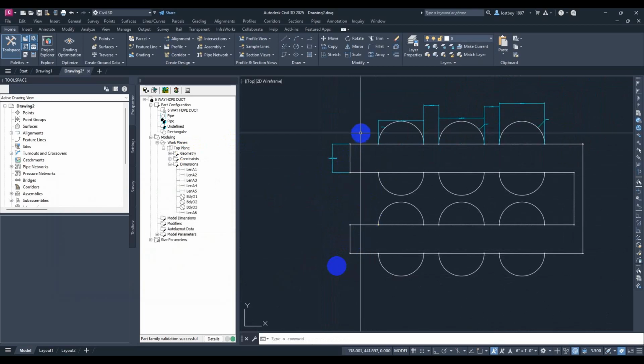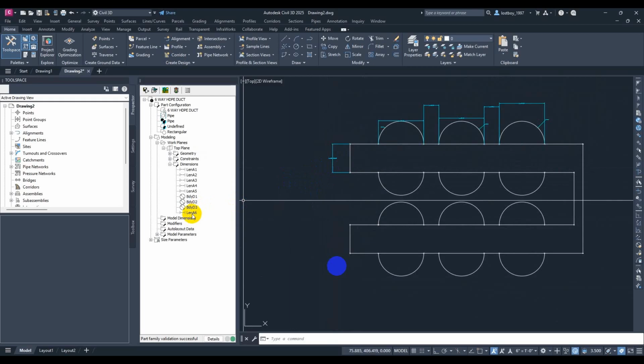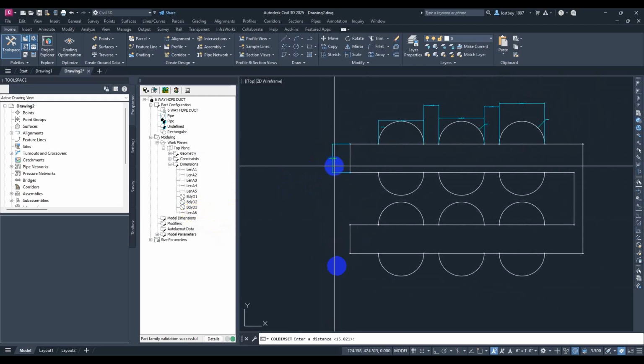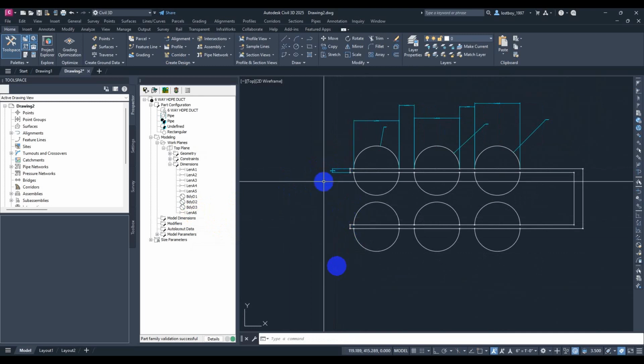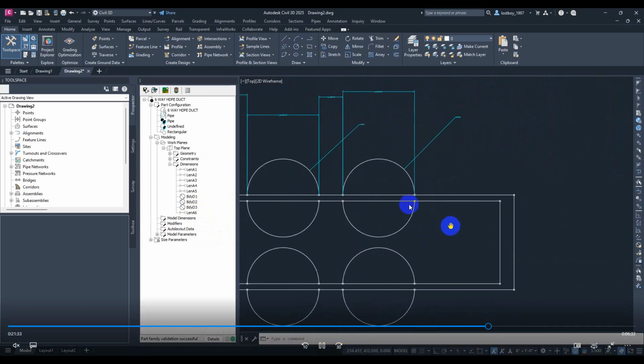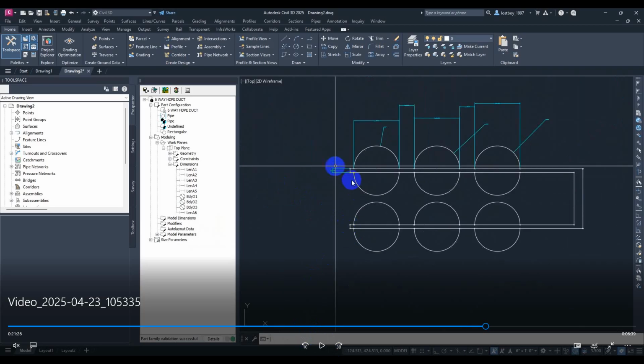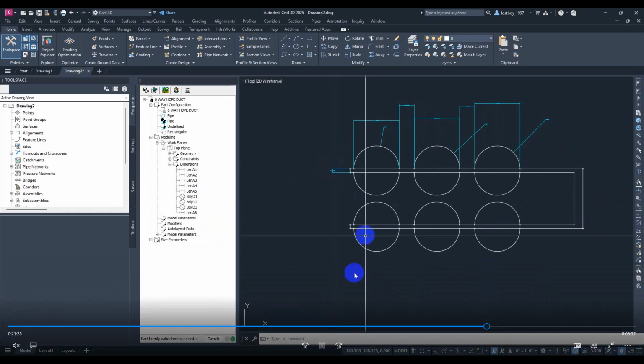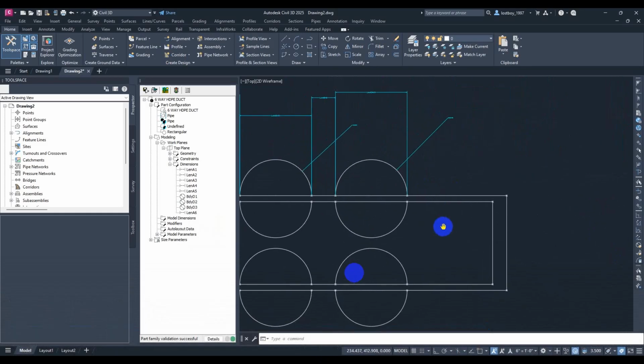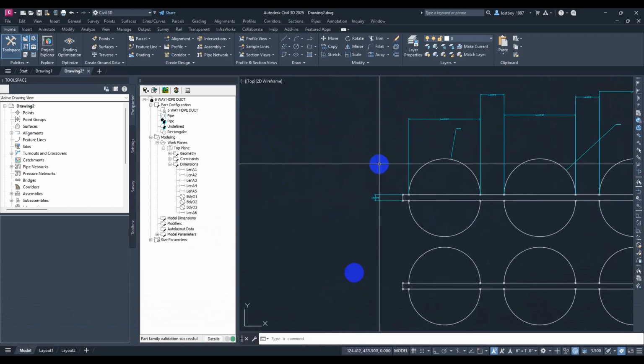And I have already made this one equal distance to the lower one. I will check also, if it's changing, it will change all. Yes, it has made the change that I hoped for. As you see, this one I didn't make equal. This part I made equal to this part, and this part also equal to the lower part, here. So that's why it looks like this. But for this part, I need to make it also equal to this part, so it is all tied together in one dimension and not leaving something free without any dimension, which will affect how it looks later. So you will find me now adding an equal distance constraint also to this one.